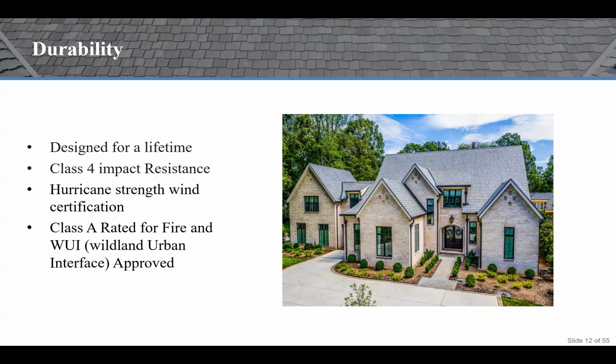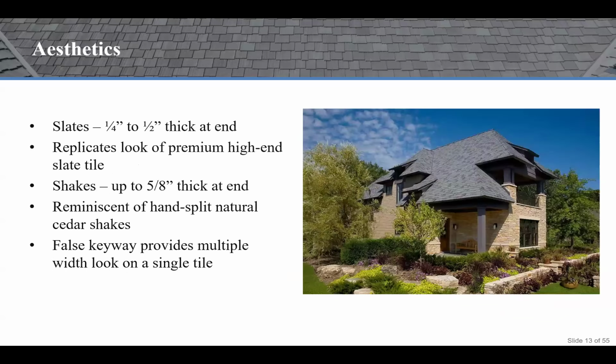Some composite roofing products are also Class A fire rated and Wildland Urban Interface approved. This is important because in several states, and as we're experiencing, where wildfires are common, the use of natural slate has been banned strictly due to the risk of fire.